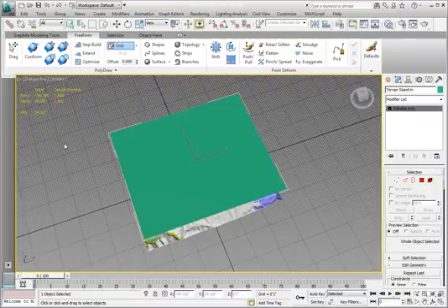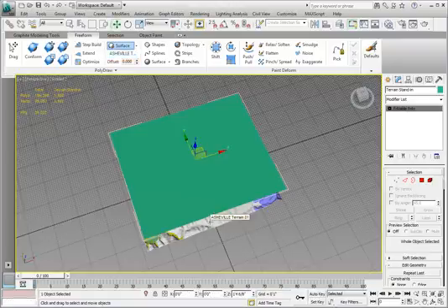In the PolyDraw panel, click the down arrow to the right-hand side of the Grid option. From the drop-down list, click on the Surface option. Click the Pick button in order to select the object that we're going to use to conform to. After clicking the Pick button, click on the high-resolution terrain located beneath our low-poly object. This now sets the high-resolution version of the Asheville terrain as our designated Conform To surface.